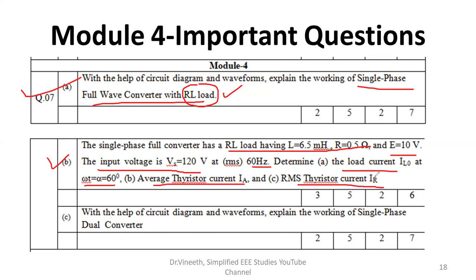Okay. So what you can do is use the formula. Cut and dry formulas are available, so direct formula can be used. You should know the relation between RMS value and the maximum value. V_RMS equal to V_M by root 2. That concept you also need to apply here.